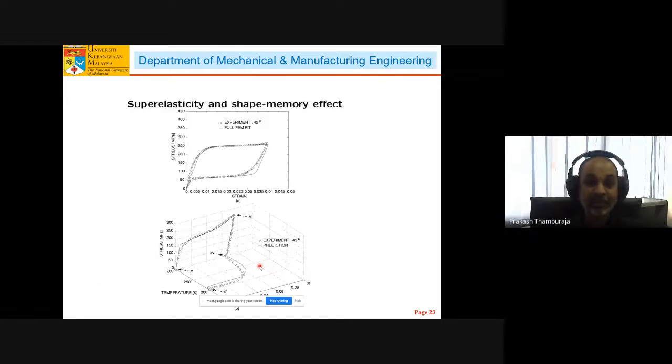It's quite some time ago. Now finally we've come to the superelastic effect. So what is the superelastic effect? This is the effect manifested by shape memory alloys at temperatures above the austenite finish temperature. This is one example of an experiment under constant temperature. You start off at this initial state, which is completely austenitic, and as you deform it, you get some elastic behavior and then some kind of elastic-plastic transformation from an austenitic phase to a martensitic phase due to phase transformation.